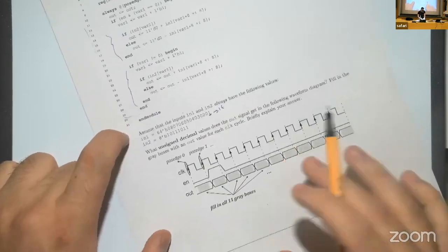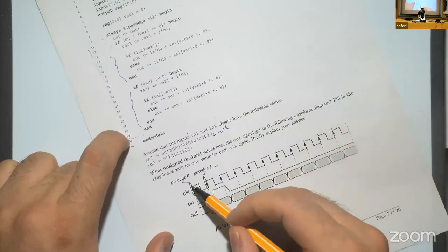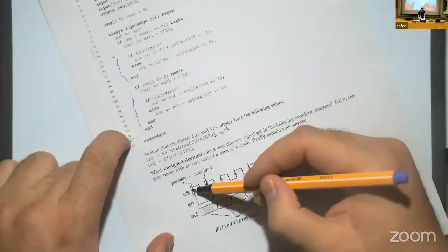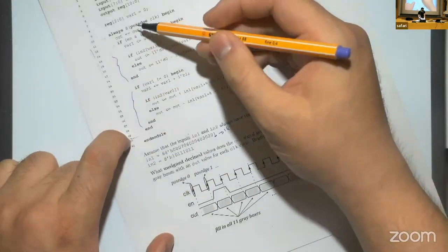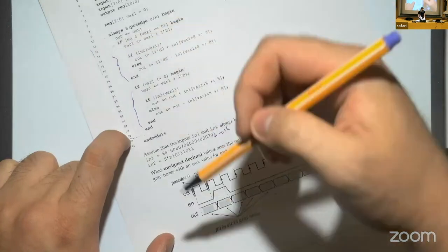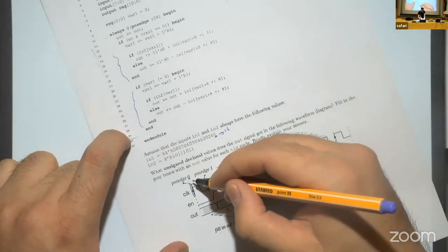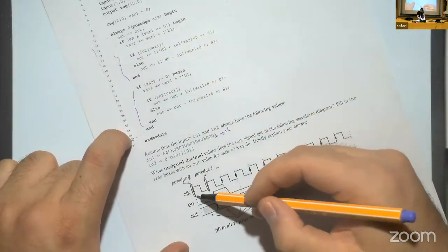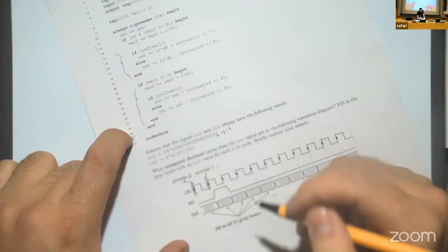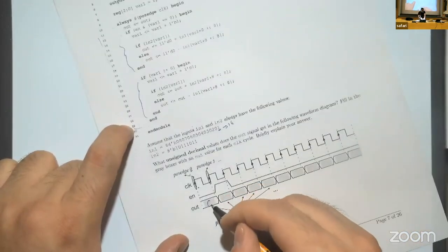So let's start. For the first one, we know that this is posedge clock, right? And this is the always block. What happens is that when we start executing this block, the variables assigned in this block are updated at the end of the cycle, which means that this posedge clock 0 will be executed here, but the results are updated after this cycle. So here we know that the initial value is 0, right? So the out becomes 0.